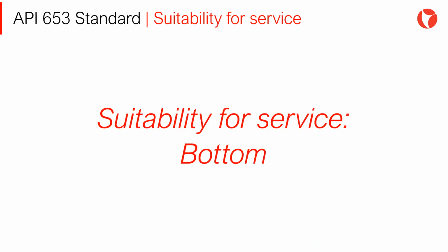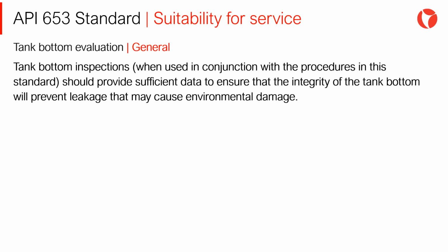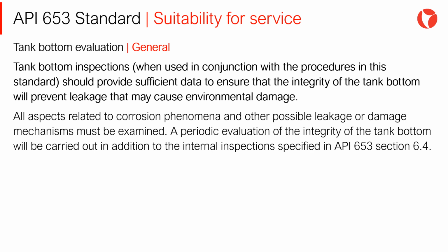Suitability for service of the tank bottom. In general terms, tank bottom inspections, when used in conjunction with the procedures in this standard, should provide sufficient data to ensure that the integrity of the tank bottom will prevent leakage that may cause environmental damage. All aspects related to corrosion phenomena and other possible leakage or damage mechanisms must be examined.